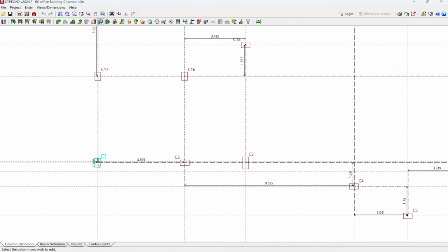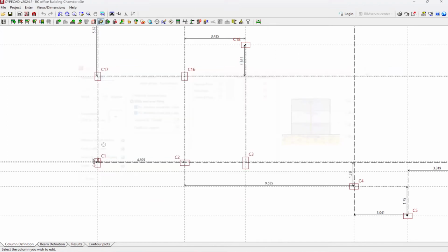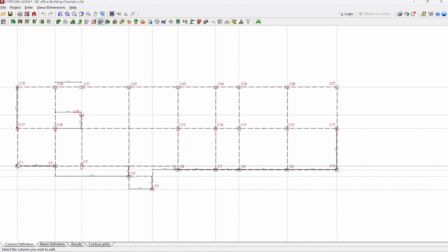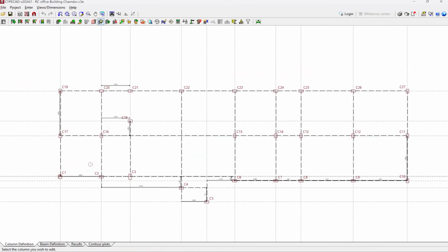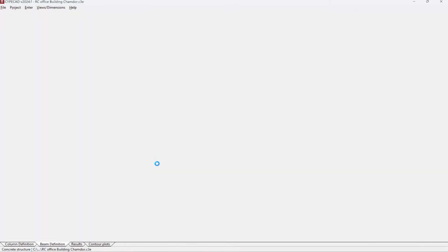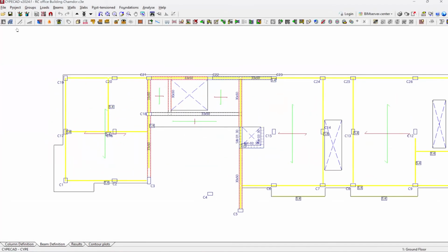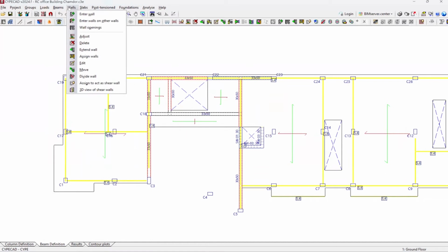You don't necessarily need to come and place it on this side. So you've imported from Revit as well and done it automatically. You do both things. That's correct. So after doing that, you introduce your columns, or the grid line imported from AutoCAD drawings. Perfect. Done that, you proceed to the beams, whereby on beam definitions, you have your beams. You want to set up the beams. You've got your slabs. You also have walls on the wall option.